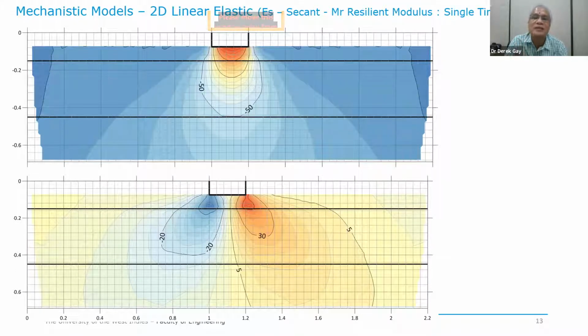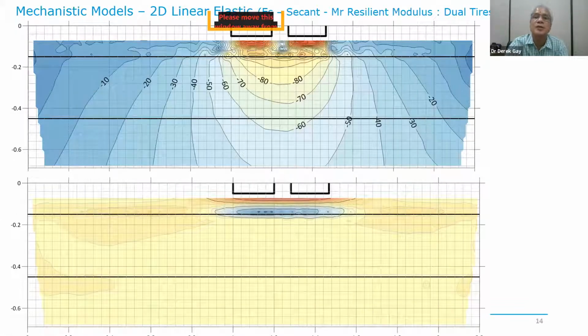So we then have to look at, therefore, the strength of the lower layers becomes very, very important. You could see it here too. So this is a failed asphalt, or asphalt compromised to half its strength. You could see it's stress penetrated, and you could see that the shear distortion in the layers has also gone deeper, fully embedded into the base course layer.